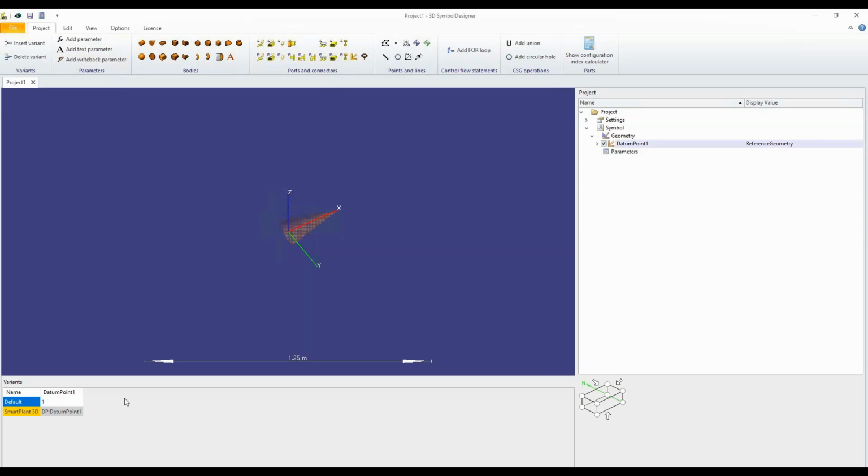And you can reuse these project files now for UPV, and you can add additional functionality in here in 3D Symbol Designer. The only additional buttons are these two buttons here, one for the angle and one for the length. These buttons can be used to add additional functionality to your symbol. They are still compatible with the export to Smart 3D. So it's not destroying or blocking your old symbol, it's just adding additional functionality. Just a little example, for all the users that have not seen 3D Symbol Designer and come from the UPV world.